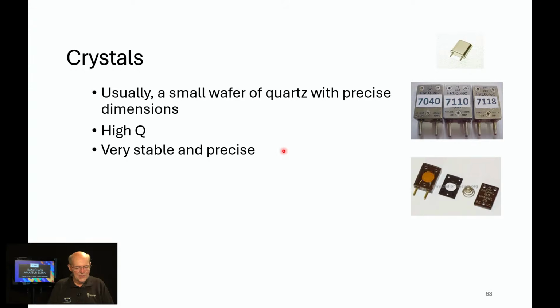And an interesting bit of history, back in the day, hams would actually grind their own crystals. They'd start with a crystal on a frequency that they didn't want and try to change it. They actually had grinding compound. You could take the crystal apart and whale away, in southern terms, on the quartz crystal face. Some people would use toothpaste, believe it or not, and rub that to lower the frequency, or they'd use pencil lead to raise the frequency, actually changing the physical size of the quartz. So a little bit of ham history for you there. I'd like to show you, I brought some along as samples over on the calculator cam.